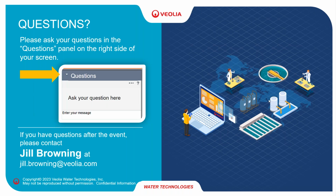In fact, Veolia offers a low pH RO process that's really geared towards acid mine drainage, and that may be a better fit. So if you have an application, let us know. We have a process called AMDRO that runs at a pH of 3.5 or less, and that provides good scaling resistance against silica and sulfate scales. And so we would have to look at the application.